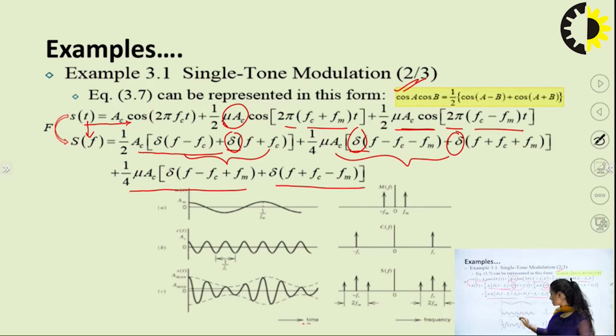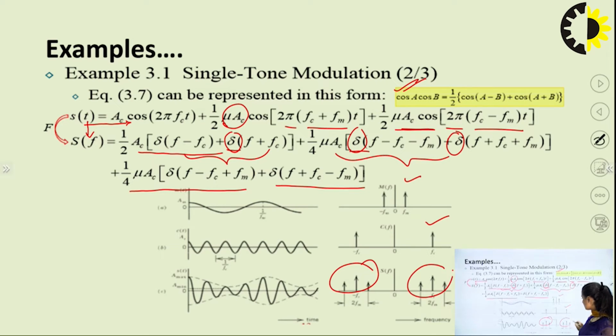So this holds true for the frequency spectrum of an amplitude modulated waveform. This is my message signal, this is the carrier, this is how I can represent an amplitude modulated wave for small m less than 1, right? These are the frequencies for my message signal, for my carrier, and the upper and lower sideband for positive half and negative half frequencies. I am representing the frequency peaks.